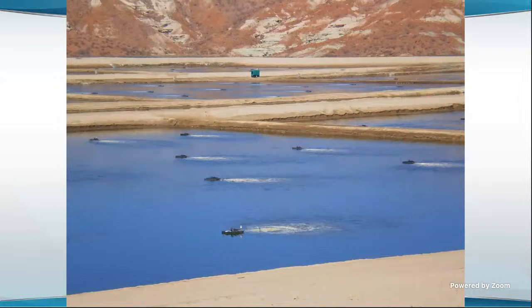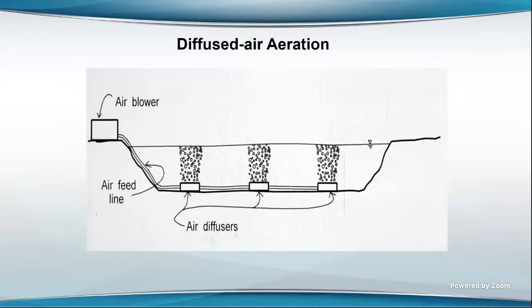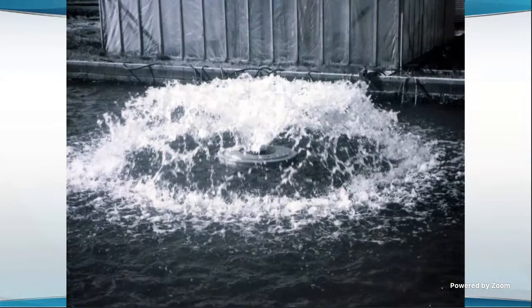This is some of them in shrimp ponds operating. You can see with the old aerators, though, you're going to see kind of what you see here, that the water's going to be going at a pretty good velocity right in front of those aerators, but the farther out you go, the slower the water movement gets. So these aerators create a lot of water movement around them. And I tell you, an aerator that sends the water forward, like a paddle wheel aerator or like these propeller aspirator pumps, are much more efficient in a larger body of water than one like that.